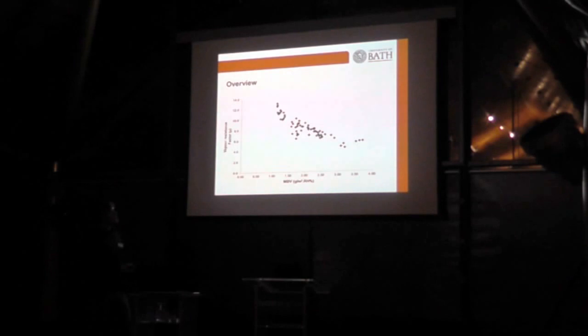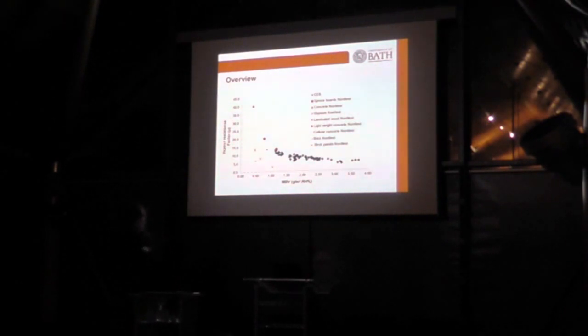So just an overview of the samples I've shown here. There's not much in the literature that you can really compare it to because it hasn't been done that much in moisture buffering values, even though there is actually an international standard to measure the moisture buffering value. The NORDTEST, there is a Japanese standard, there's a German standard, but there's not that much reference, especially not for earth building materials. So I still compared it to the NORDTEST results they had for concrete, gypsum, laminated wood, etc. These were averages they made over 3 or 4 different laboratories, different universities.